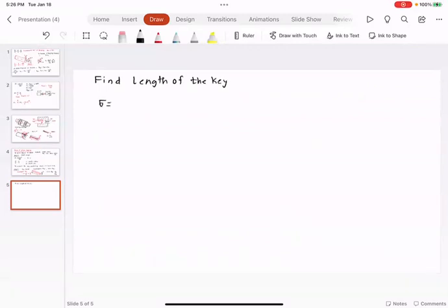using the equation sigma crushing is equal to F divided by (T by 2 times L). The only unknown here is L, and then check the key for shear.